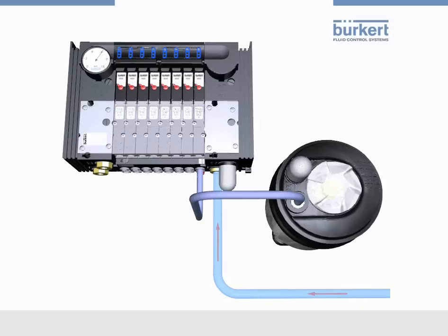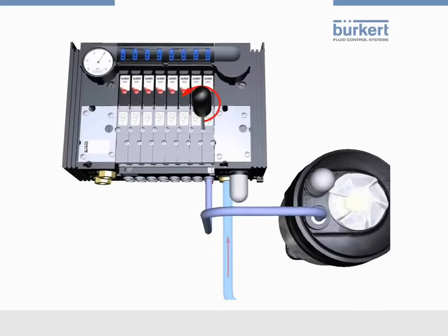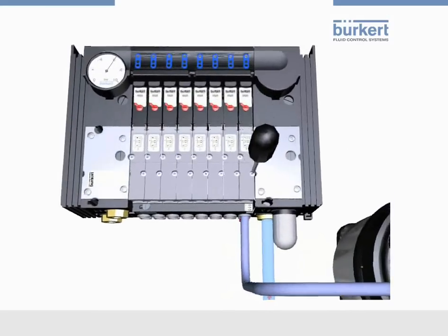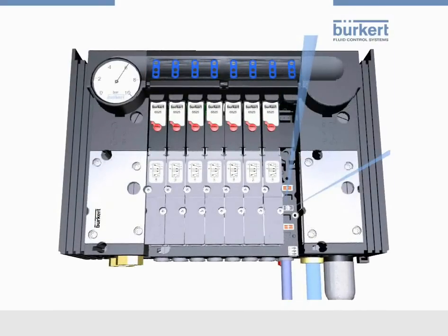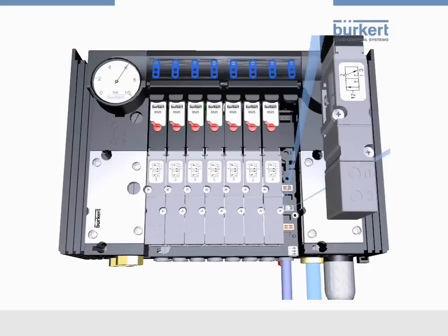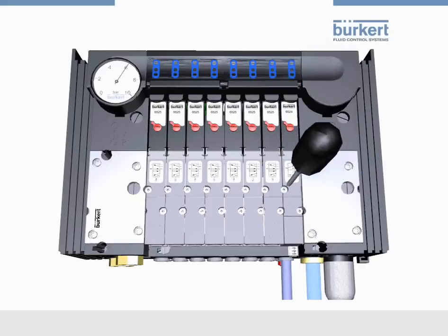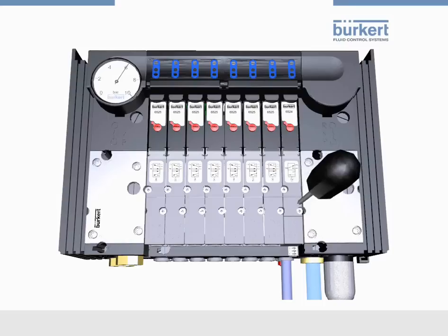Let's presume that a pneumatic valve on an automation system is damaged and has to be changed. At first, the valve is removed by loosening both fastening screws. By doing this, you see the pneumatic module with the integrated hot swap function. Only a small air jet can exhaust, meaning the air pressure on the entire block doesn't collapse. A new pneumatic valve can now be mounted on the empty valve space. The new valve is ready for operation immediately.